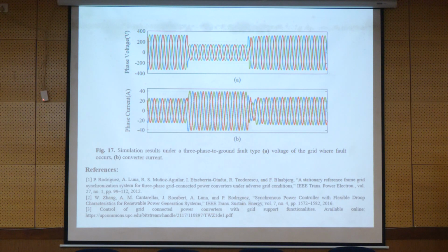This is one thing, and then we also have some loads based on power electronic devices. For example, we have electric vehicles. Electric vehicles are charged by the charging station, which converts the sinusoidal AC to DC. So they are also power electronic based loads, which also provide lots of harmonics for the grid. And then they have also new technology based on fast charging devices, so it provides a big spike over the grid.